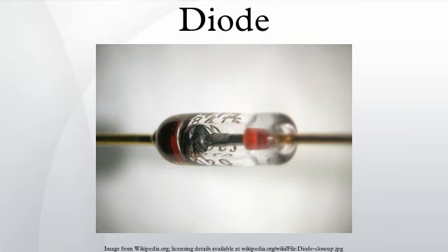Current steering. Diodes will prevent currents in unintended directions. To supply power to an electrical circuit during a power failure, the circuit can draw current from a battery. An uninterruptible power supply may use diodes in this way to ensure that current is only drawn from the battery when necessary. Likewise, small boats typically have two circuits each with their own batteries, one used for engine starting, one used for domestics. Normally, both are charged from a single alternator, and a heavy-duty split-charge diode is used to prevent the higher charge battery from discharging through the lower charge battery when the alternator is not running.